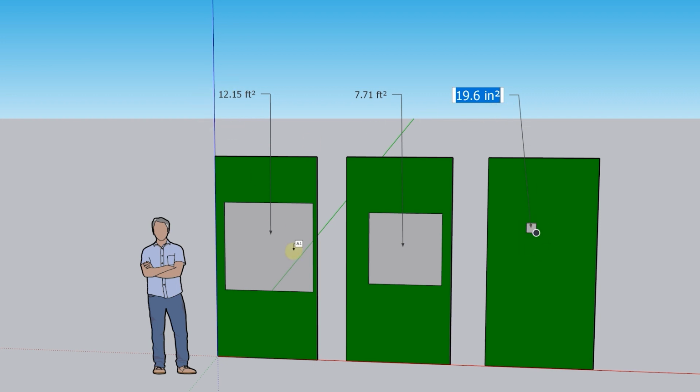But this is the aggregate of all the different cracks and crevices inside the house. And you can see, this is essentially leaving a window or door open. That's how leaky your house is with the first two. So unless you're sealing the panels on the house and dealing with the air barrier on the outside of the house, you're gonna have a fairly leaky house.